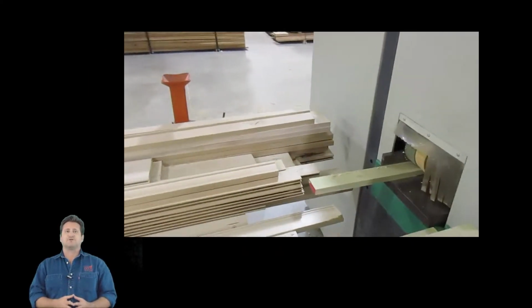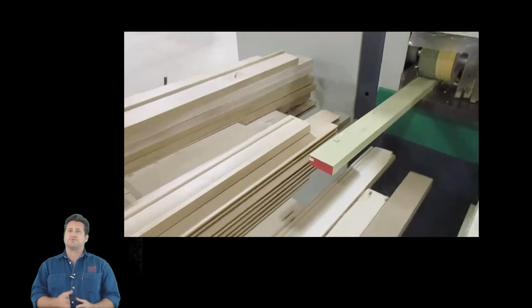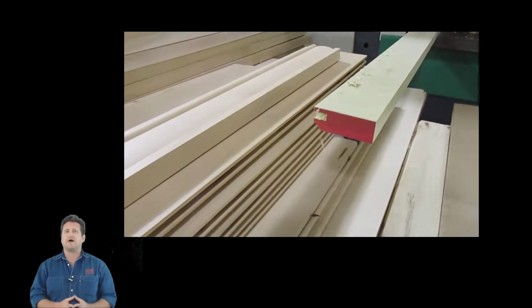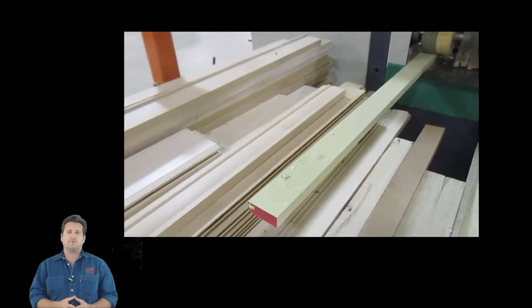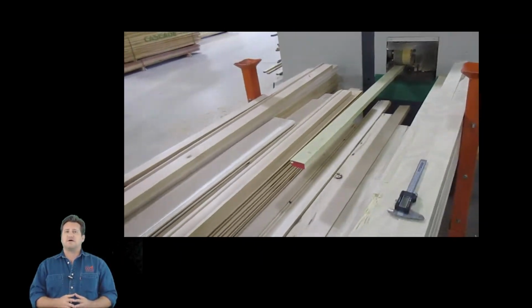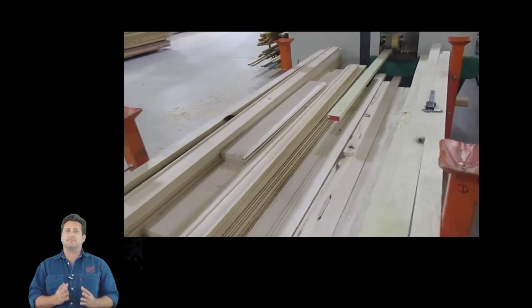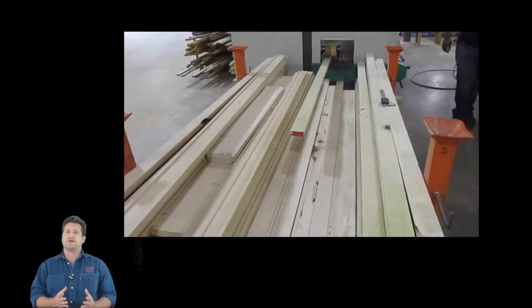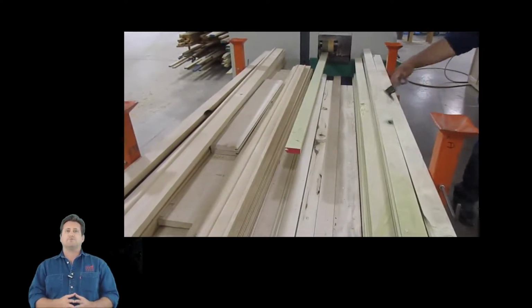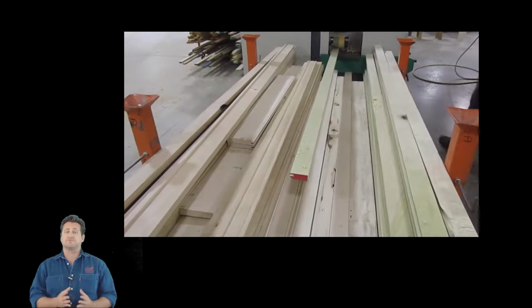Now, the molder will surface the rip on all four sides with a finish tolerance of within several thousandths of an inch. The output of the molder is a length of shaker style stock which is ready to be cut into the components that will make up the frame of the shaker door. A video of a molder producing a piece of shaker door style is being shown.